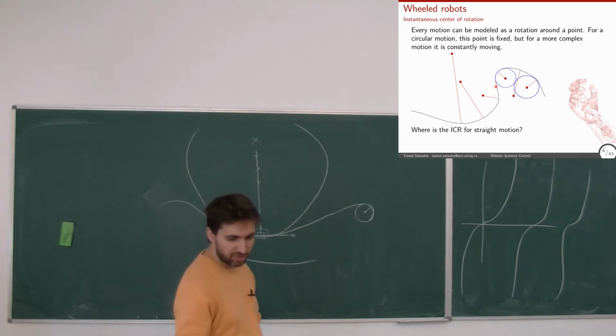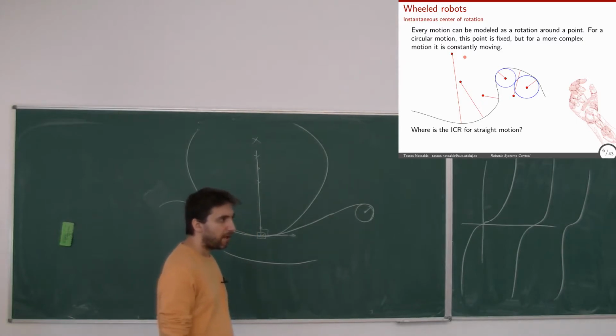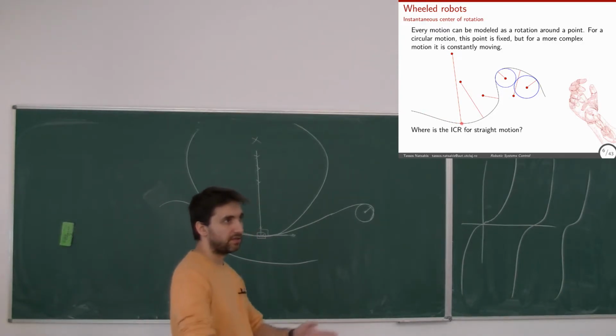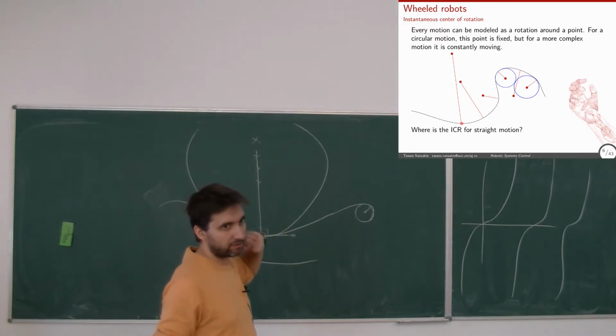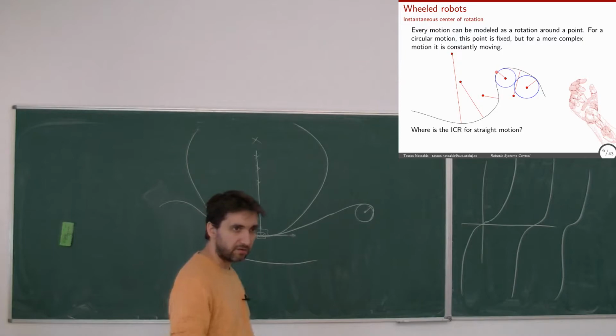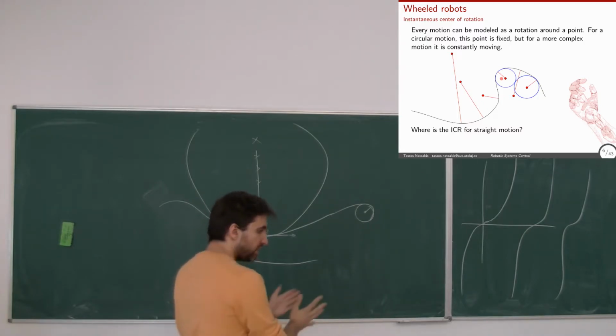Good. So this concept we will use a bit today, this instantaneous center of rotation, because I can drive the robot saying, not go left by 1, 2 degrees, whatever. Say, okay, move now with the center of rotation at that distance, at that position. So what we will control is the length of this. So we go the other way around. The length of this defines how curved is my turn. And by changing this length at every part of my trajectory, I change how much left or how much right I'm turning.